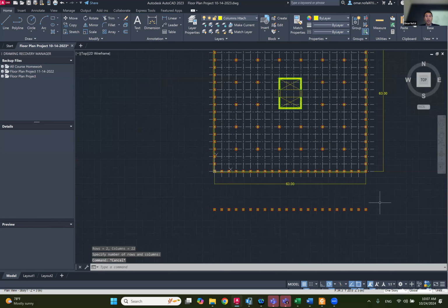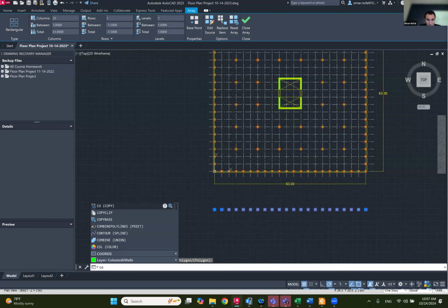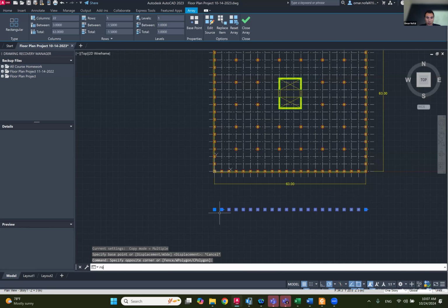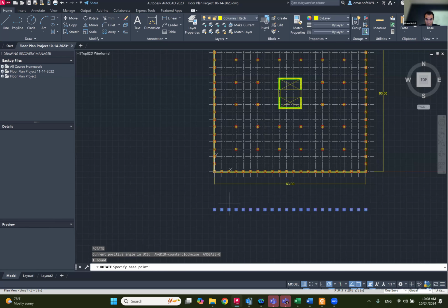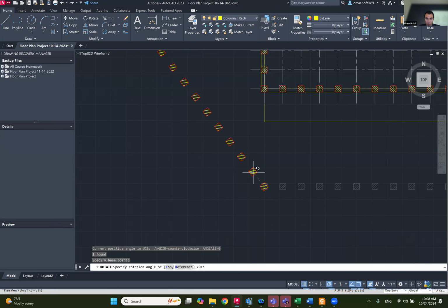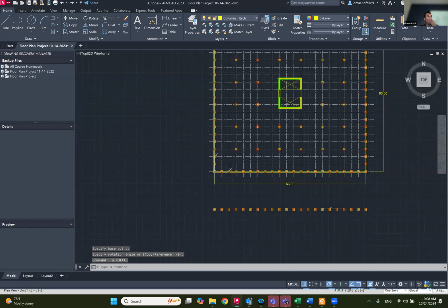Computer is very slow. And then you can rotate it. Like I can make this and I can copy. Let's see, there's copy. Let's say rotate. Specify the base point, which should be in the middle. And then if you hold control while doing this, I believe it should copy. So that's how I would do it, so that you don't have to draw them one by one.